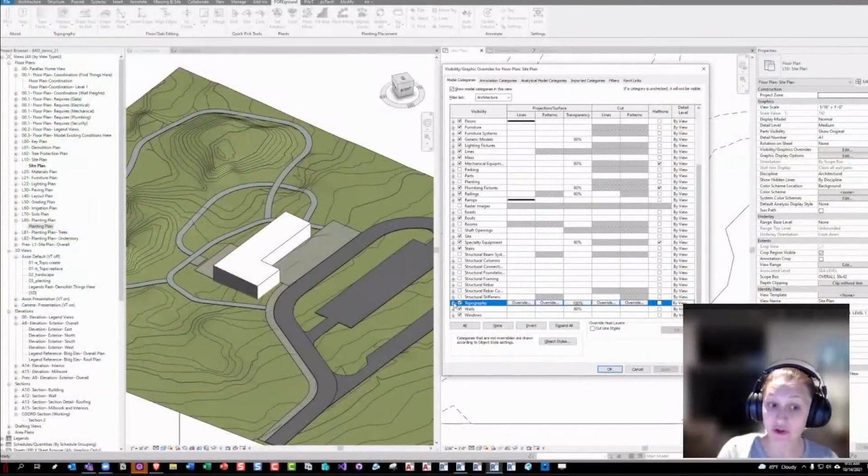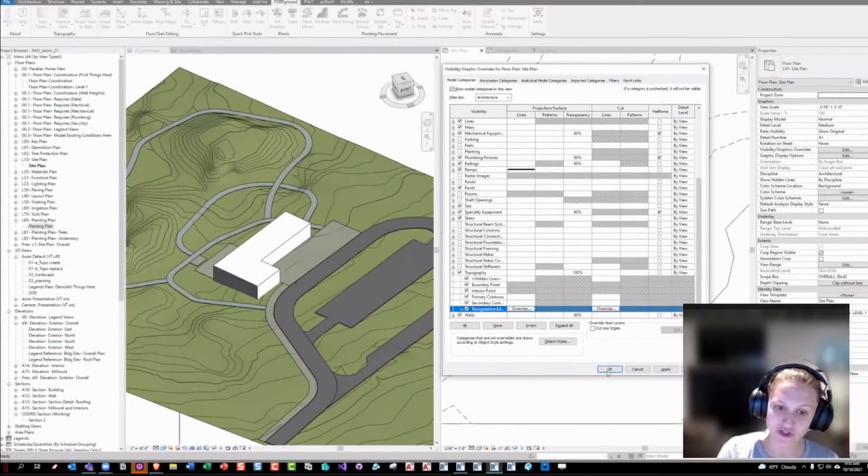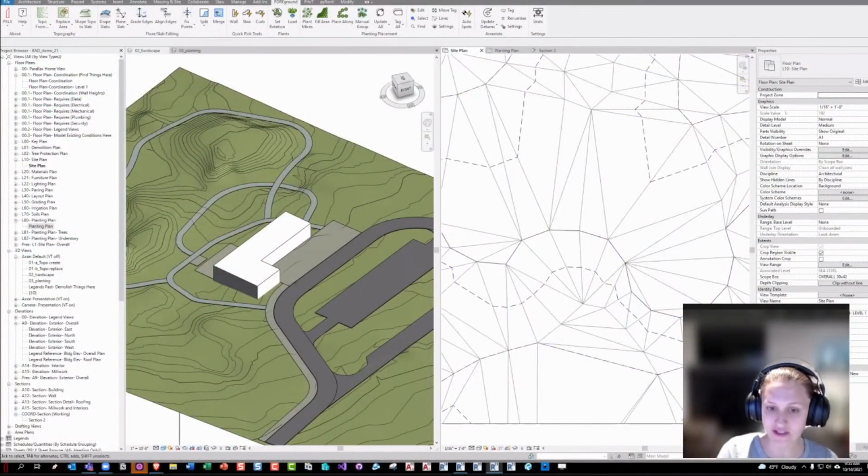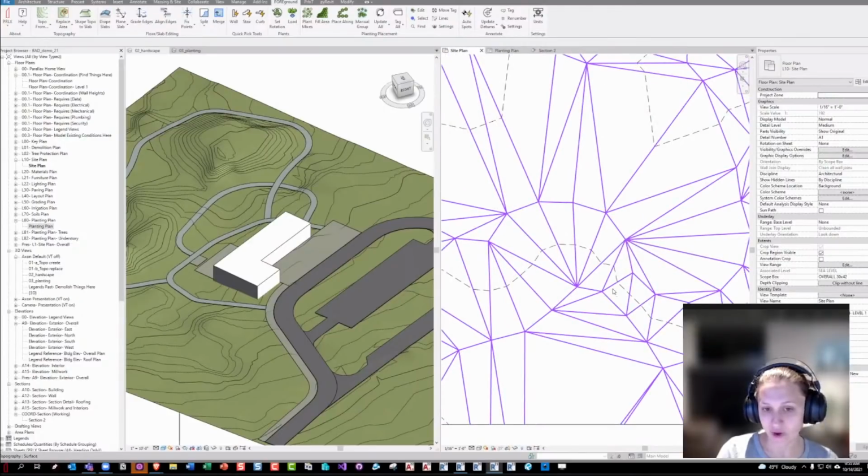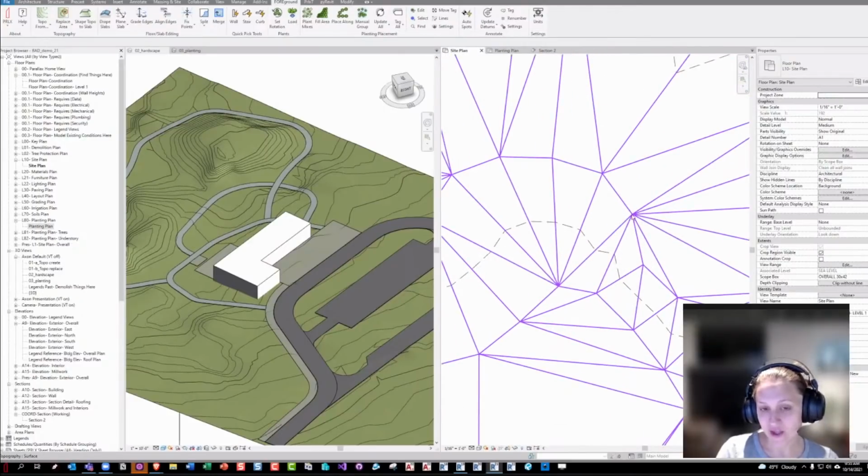It is useful to know that there are times where you want to fix things like this. If you turn on your triangulation edges, you can start to see why these things happen. Basically, all these weird topography things are just a result of interpolation along those edges. So understanding why it's doing that is helpful if you really need to fix it.